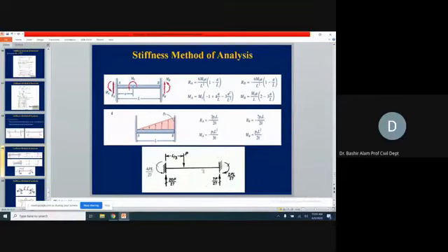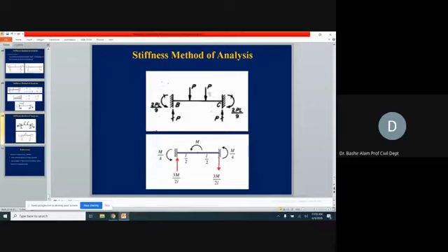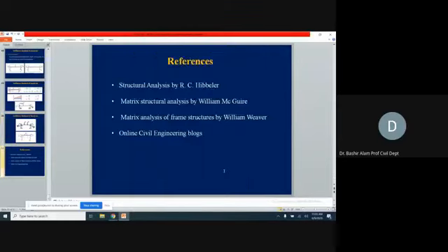If the point load P is off center, let's say at L by 3 now, we already have the case of A and B, and we have the equation PAB squared divided by L squared, something like that. So here now these values are given. Then if we have two point loads at the 1/3 locations, these will be the member end moments generated. If we have a couple now within the member at the middle, these will be the member end moments generated.